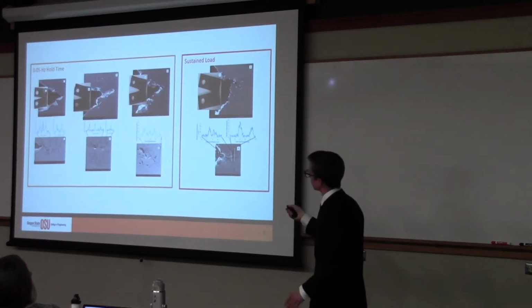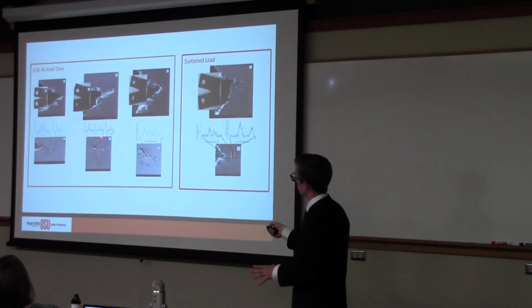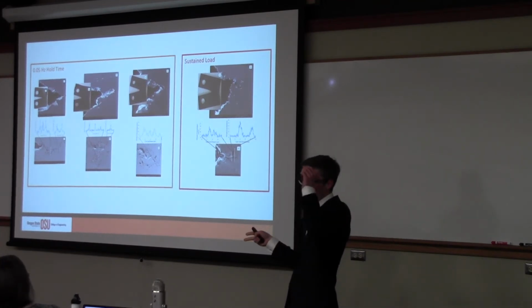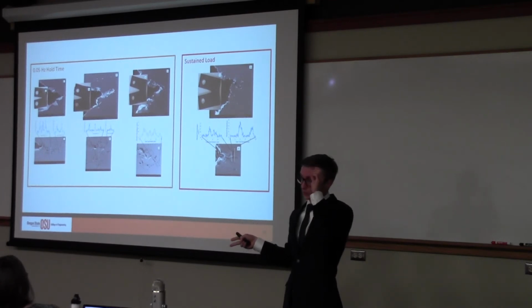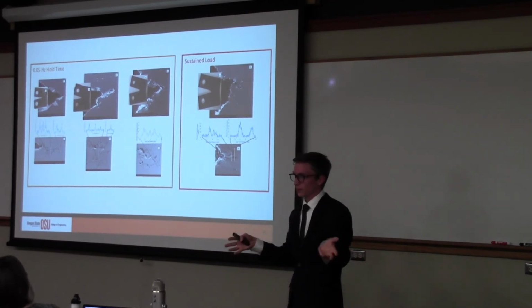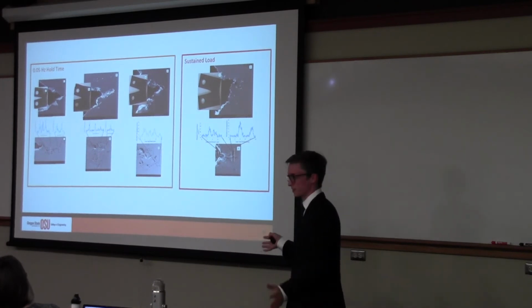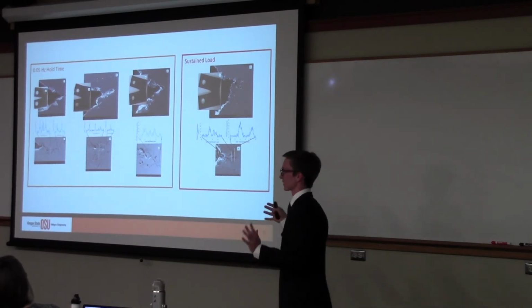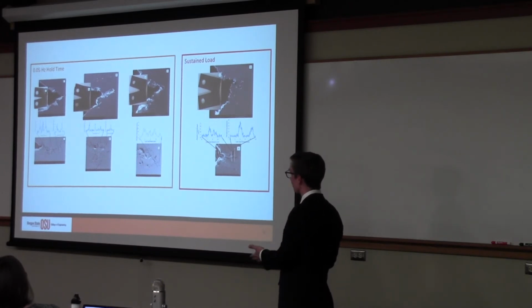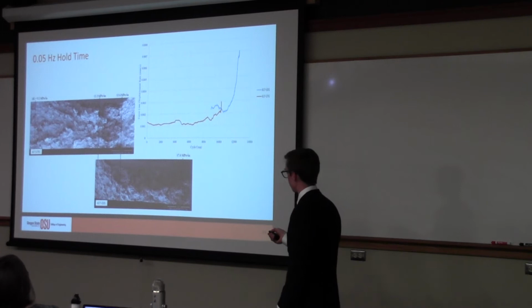See that? So this next plot is going to be showing the fracture surfaces of these two samples again, where we had large force line displacements, and this is where we stuck the extensometer in, and we got the force line displacement rate. And it becomes very clear that a time-dependent mechanism, not like it wasn't clear already, but it becomes extremely clear that the time-dependent mechanism is at play right at the transition in our fracture surface behavior. At the end of 27G, the orange line, we get this spike up, and right near the beginning of 32G, the force line displacement goes way up. You get this hockey stick plot.